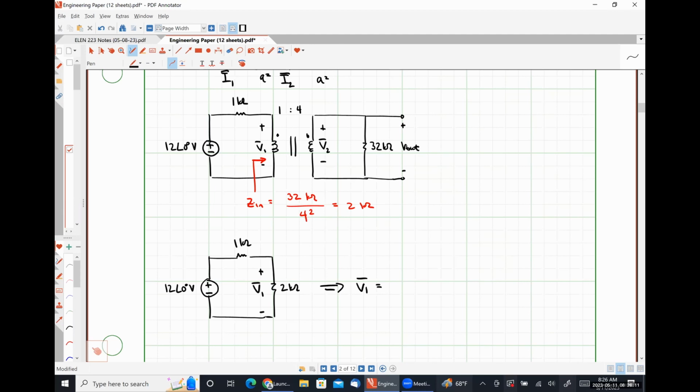So remember Ohm's law, right? V is equal to I times R. So if we're finding the voltage drop over the larger resistor, the voltage drop should be the larger one. So just to move things along here, we'd have 12 angle 0 volts times 2 kiloohms over 1 kiloohm plus 2 kiloohms, which would be equal to 12 times 2/3, which is 8 angle 0 degrees volts.